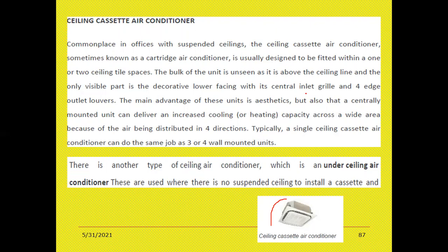The AC is separately located at the ground floor of a building where the entire room is wholly filled with the air conditioner, right? While the expansion valve and the evaporator or cooling fan, the air handling unit, are housed in a separate room. The cooling coil is fixed in the air handling unit.